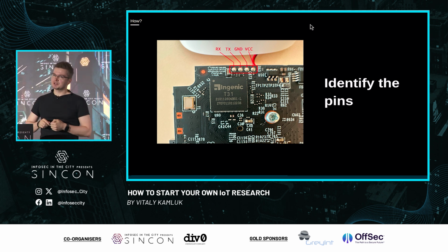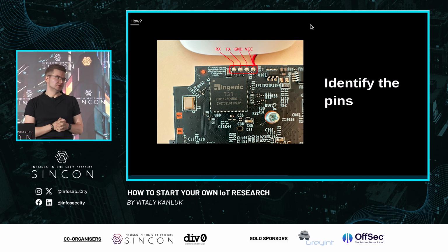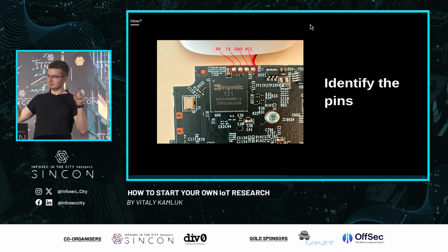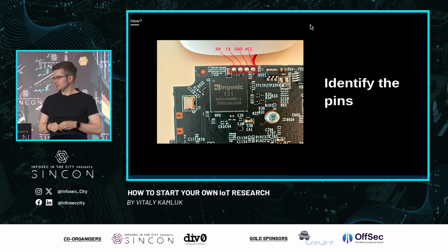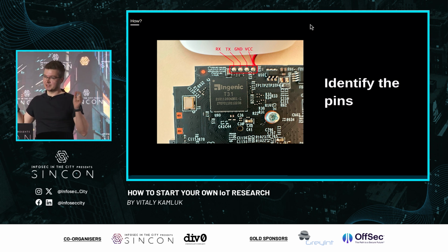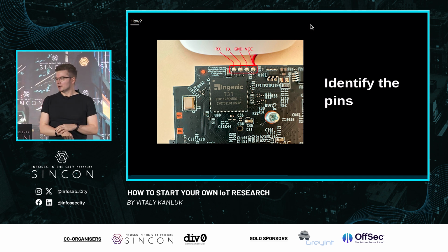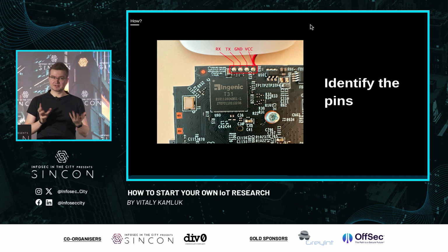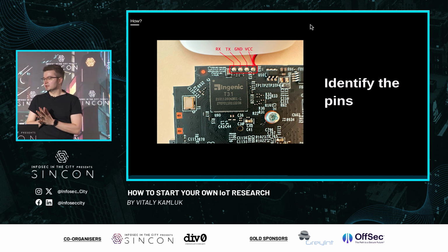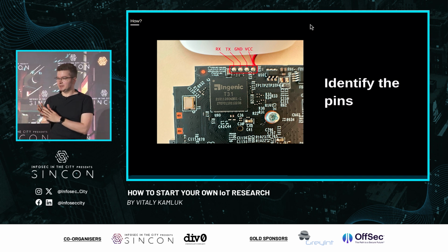So then you switch the multimeter to a continuity mode that shows whether 2 points are connected, whether there's a circuit without any blocking. Of course, we're dealing with a powered off device, so it just checks the continuity of that path, and if it exists, that is the ground pin. So that's already something. Second, you can figure out where is the voltage, the VCC pin.